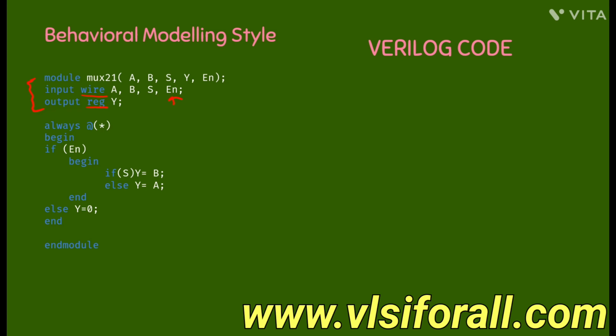Followed by this, we have the always @ statement followed by the sensitivity list. As we all know, the sensitivity list for a combinational circuit can easily be written by mentioning a star. This means that any change in the inputs will create a change in the functionality. But if we look deeper into the circuit, we can see that only a change in enable or a change in select line should create a change in the output.